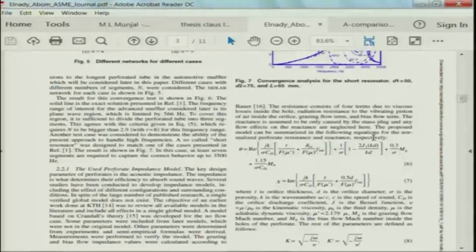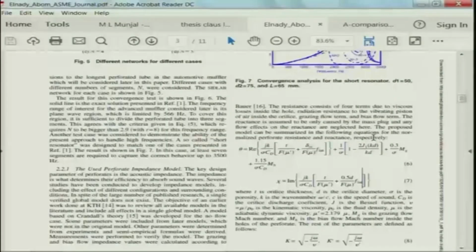They can be perforated mufflers, very complicated ones like the one the photograph showed in the beginning of this lecture, where you have a 4 duct interacting system, 3 perforated pipes and the big annular cavity, which contains a big elliptical or circular cylindrical shell that contains the 3 perforated pipes. So, it is a multiple interacting duct problem with multi path propagation.